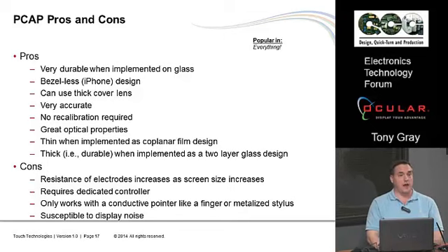You can also, because of that concept, do a bezel-less design because now you can have one piece of glass around the entire top of your display, one solid sheet. Because again, the whole idea is we're projecting this electric field, so we can project it through whatever we want. Glass, a piece of acrylic, you could even, in theory, put it through a piece of wood, although of course that kind of ruins the idea of a touch panel. But it doesn't have to be opaque. The point is it just has to be able to allow the electric field to go through it.